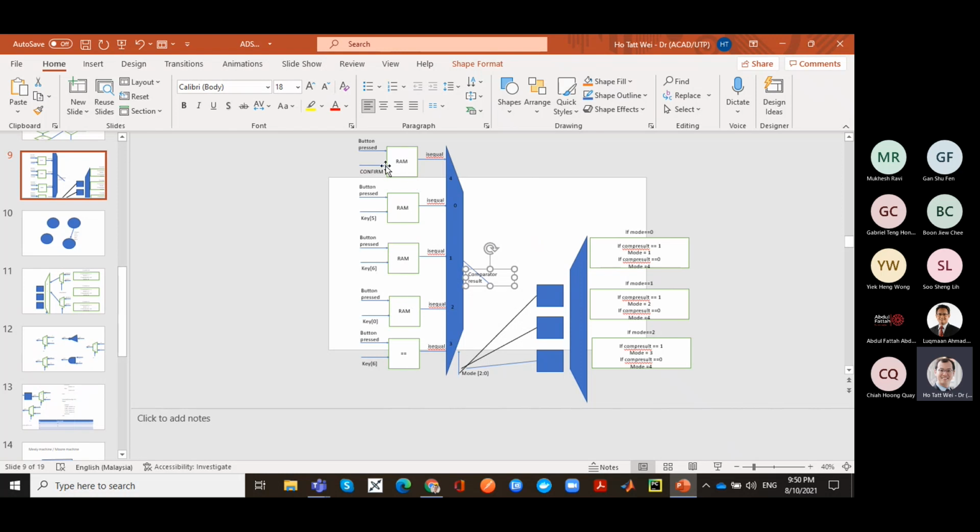And I can use a RAM to actually program the computational operation. And if I find that I don't really like it, or it's not the best way, or I want to change the function of my circuit, I can straight away go in and reprogram the RAM, and suddenly it will perform a different function. So I can change the computational operation at the particular mode by reprogramming the lookup table.